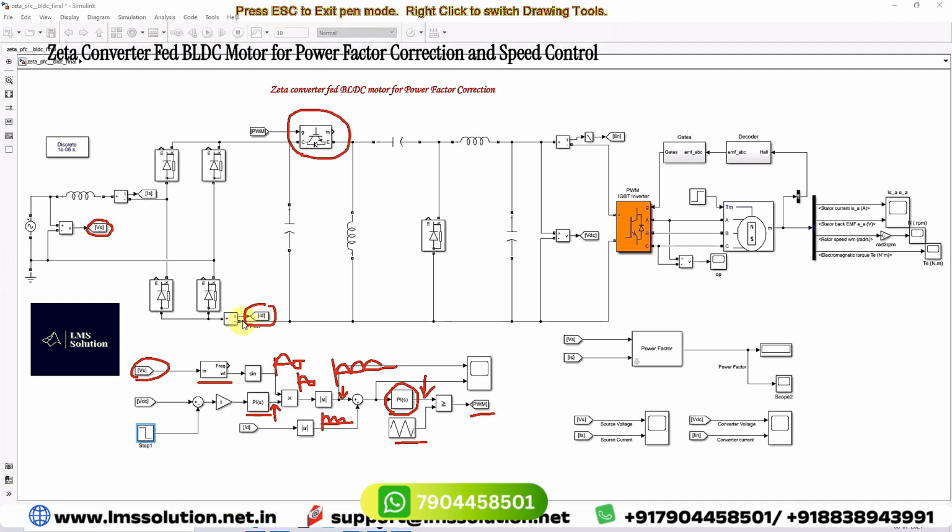It is going to change the nature of this diode rectifier current to near sinusoidal. Because of changing this current nature, it also changes the nature of the source current. So this is the working of the power factor correction circuit.